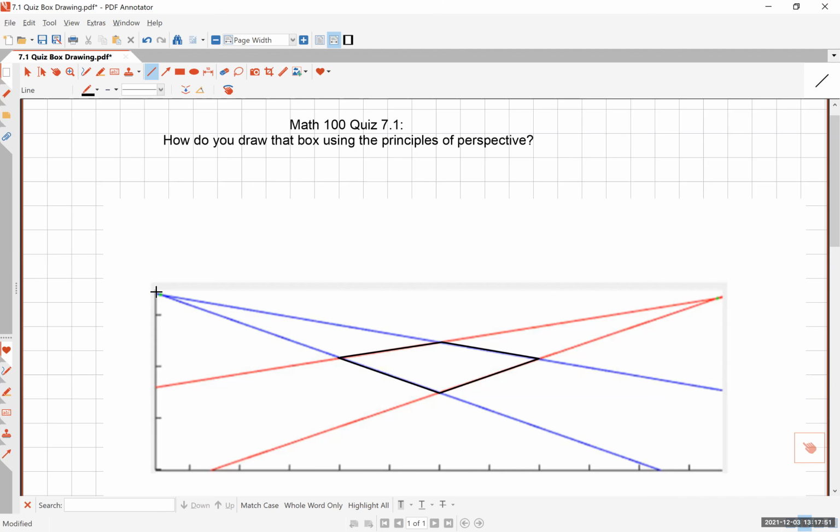Now comes an interesting part, and this is where these points called vanishing points become relevant. The first thing you should do is to draw the vertical edge, the one that's closest to you. This is the vertical edge that is closest to your eye as you are drawing this. I try to draw this at 90 degrees, and it doesn't matter how tall it is. You don't want to make this too tall. I'm going to draw a rather shallow, not so deep box. This is the edge that I'm going to use as my reference.